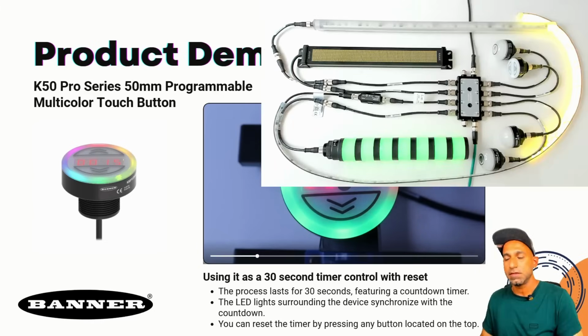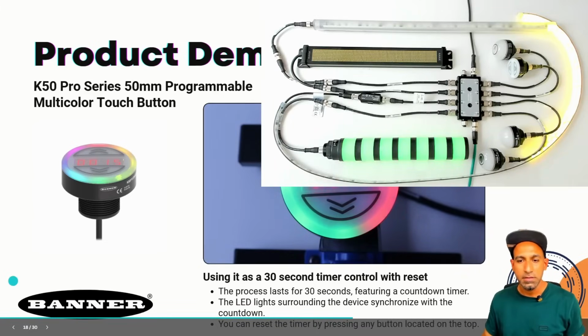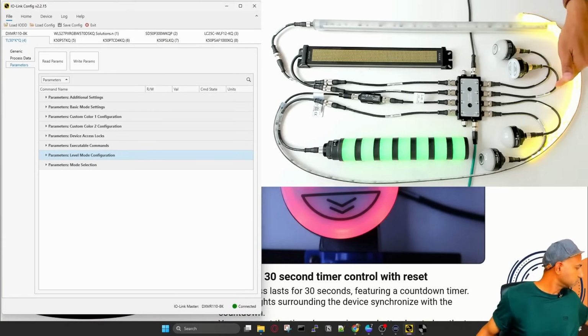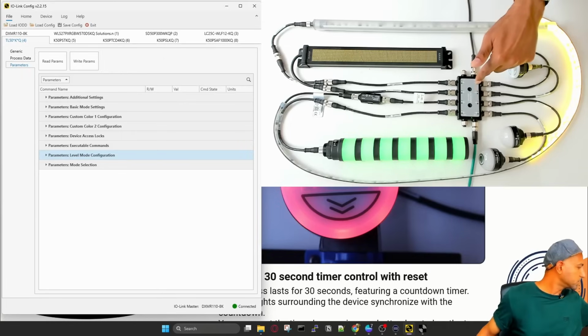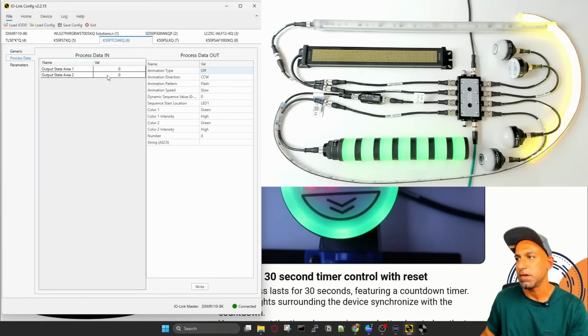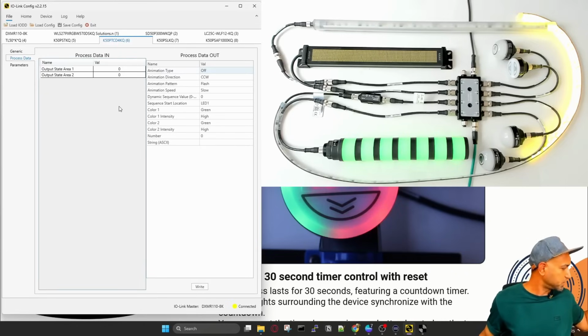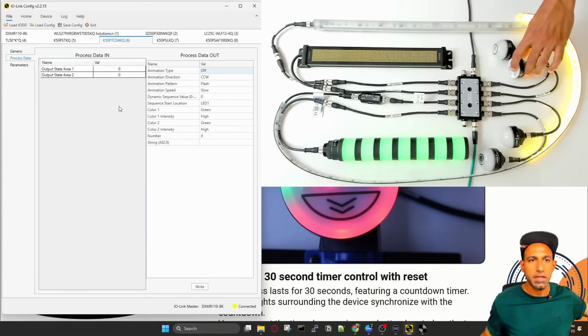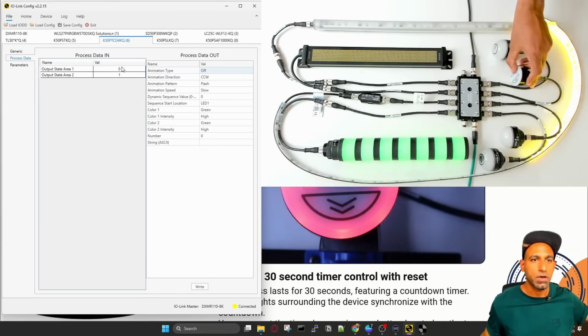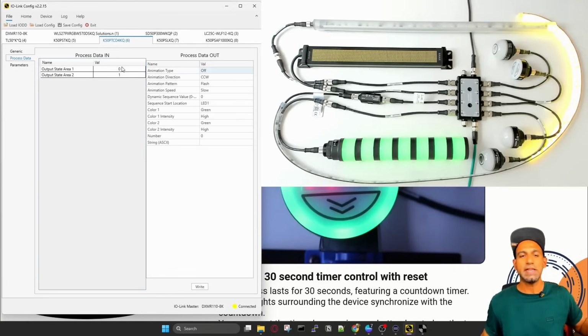So I will open up my PLC, my camera, and there is your IO-Link configurator. Now this button is connected to my port number 6. So port number 6 is over here, and that's my button. You can see the output state area, right now both are 0. This is showing you which sensor has been triggered. So if I press this button here, you can see one of them is now turned to 1. This is giving me the signal. If I press the other one, I should get the 1 on the other one, right? So this is like reading the feedback, reading the input from the user.